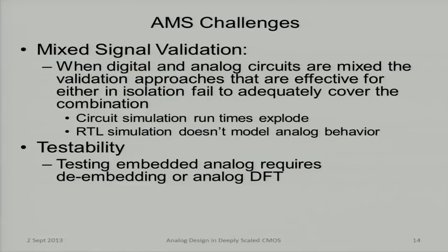If I were to use the analog methodology for validating these circuits and use simple circuit simulation, what I find is when I'm throwing the digital circuits around it, the number of transistors is going through the ceiling, and the run times that I would get from circuit simulations explode. It's really not a viable approach to take the entire system in a circuit simulator. But conversely, the RTL, register transfer level tools that work very effectively in the digital realm, how do I explain impedance to a register transfer level model that only understands ones and zeros? So instead, we end up needing to use mixed signal tools that somehow meld these two things together.